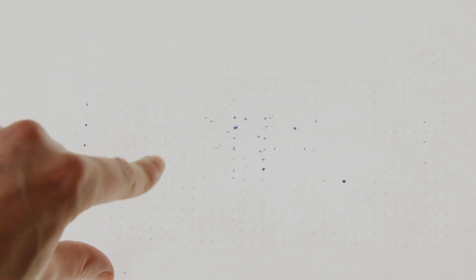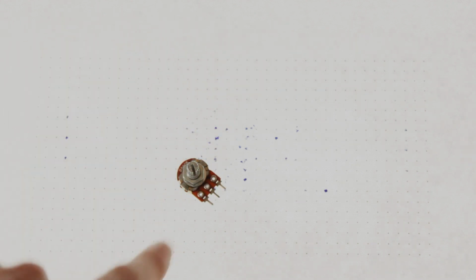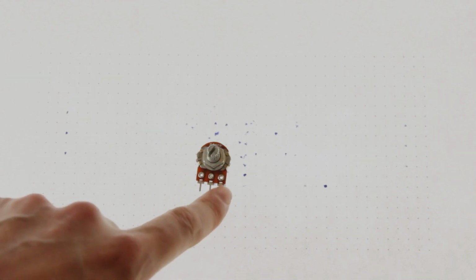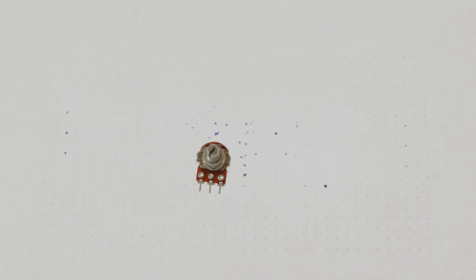And I've also printed off a sheet with all these little dots, and they are just as a guide that I can use. Because obviously I need to have the right spacing, the right pitch for the 556 timer, as well as things like the potentiometers, because these will be mounted directly onto the PCB.